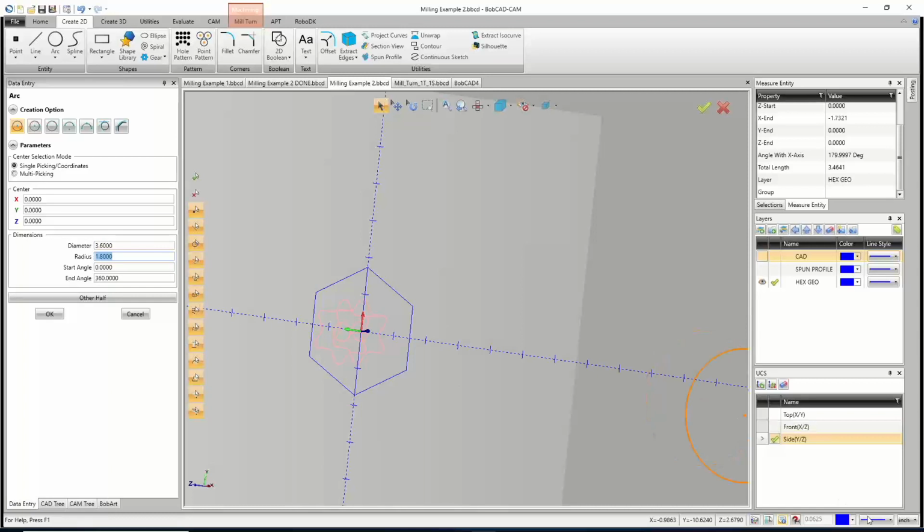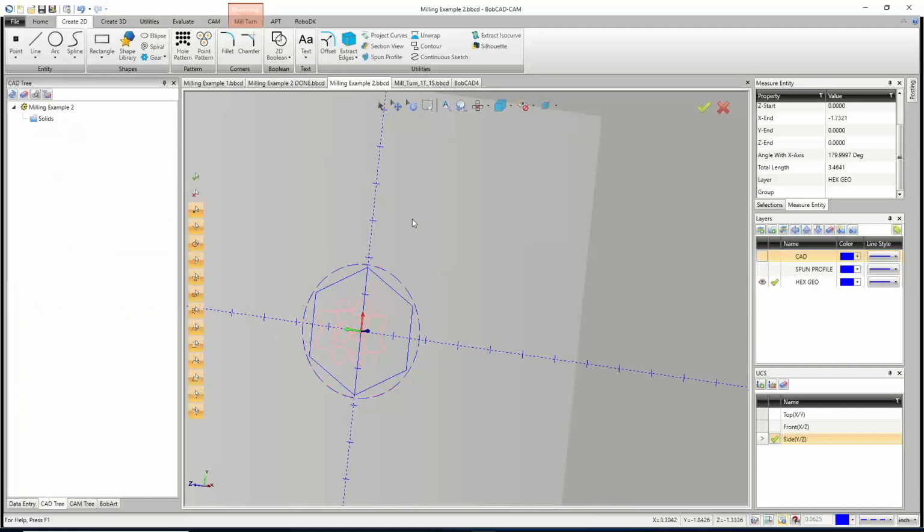And before I finish that, I'm going to go to the bottom corner of the screen here, down here, and change to a dotted line style so that when I hit OK, that line gets created as a dotted line automatically. Now I could just use my select tool and get rid of that construction line I made a minute ago just to get it out of the way. So now I'm going to tell it to use this as an open pocket. I'm just going to let it work its way around there. And we got a little bit of meat still, right here, but not so much right there.